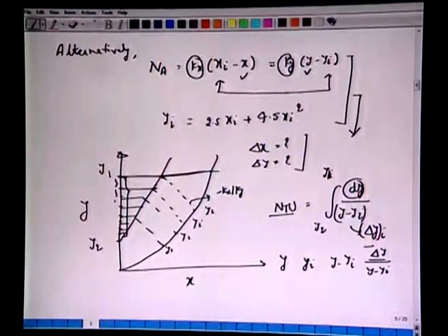It is a good practice to keep it uniform between two domains y1 and y2. Then you will take several such points 1, 2, 3 etc., maybe 10, and if you add all this, the summation of this column will give you NTU, number of transfer units based on this gas phase y.